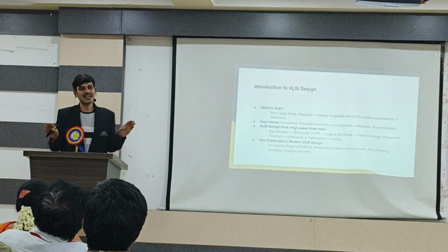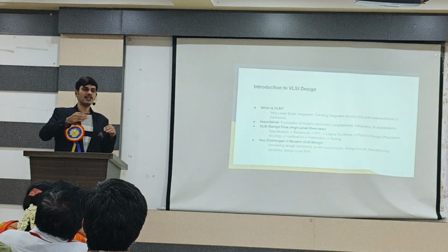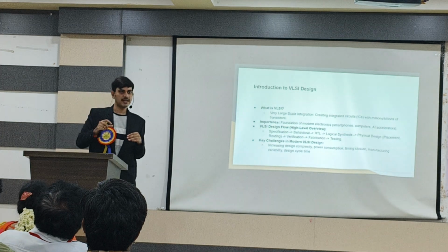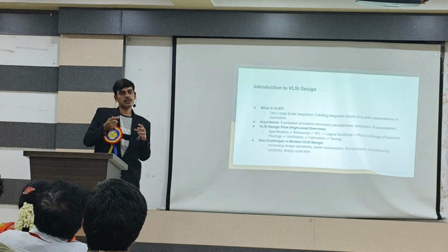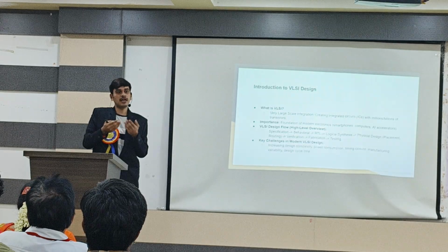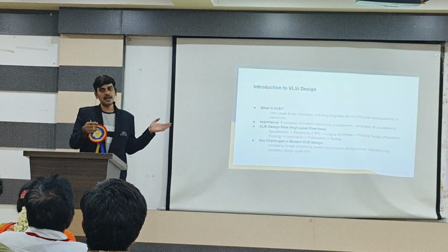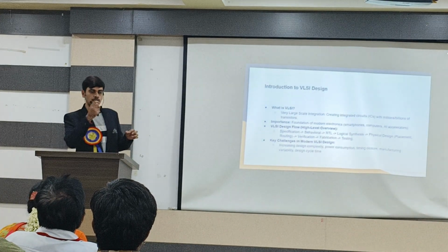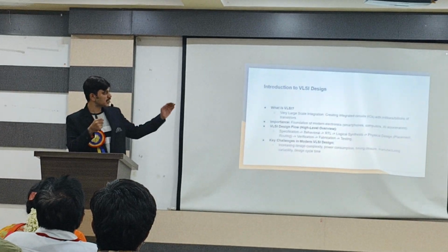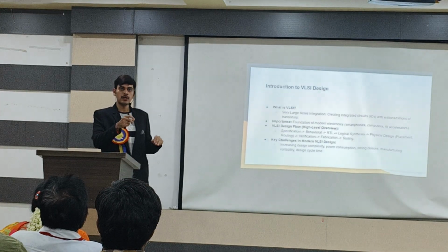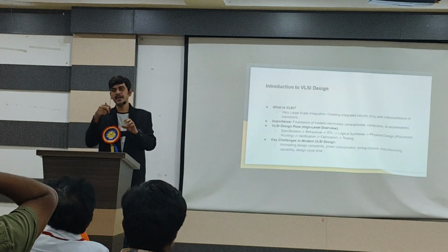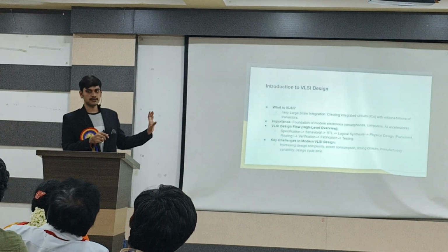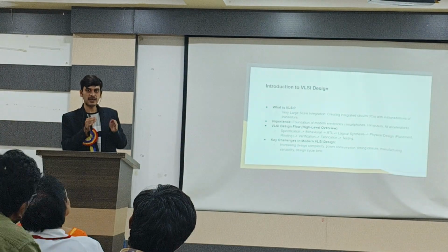I am very happy, but the real challenge comes further, because once the chip is fabricated, we get the chip back and we have to test it. We have to check how we can test it. From there, the testing is done with scan chains. You have heard about scan chains, right? During the design time itself, we need to insert scan chains so that when the chip is out, they propagate patterns and check whether the chip is working properly or not.